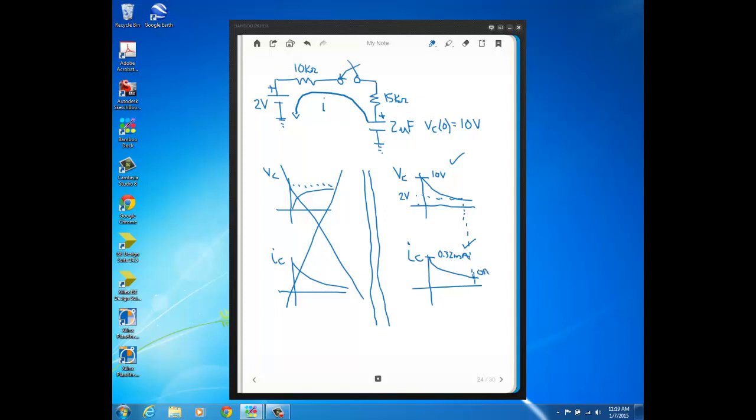And once the capacitor current becomes 0, the capacitor is finished discharging. So that's what's different from the previous discharge problem: anytime you have a discharging capacitor where in the discharge path there's a voltage source, the steady state voltage, the voltage that the capacitor discharges to, will equal that source voltage that's in the discharge path.